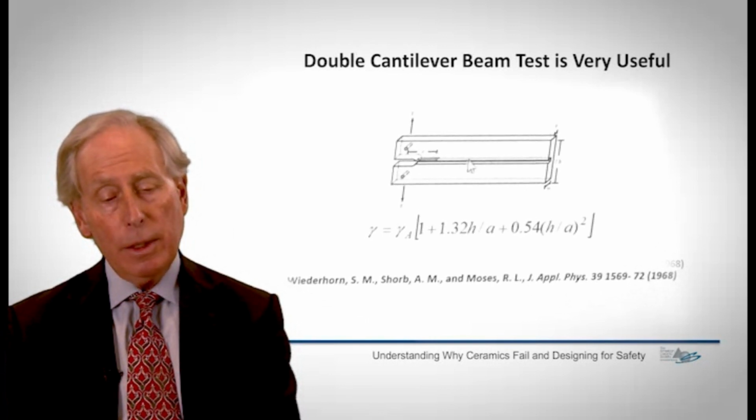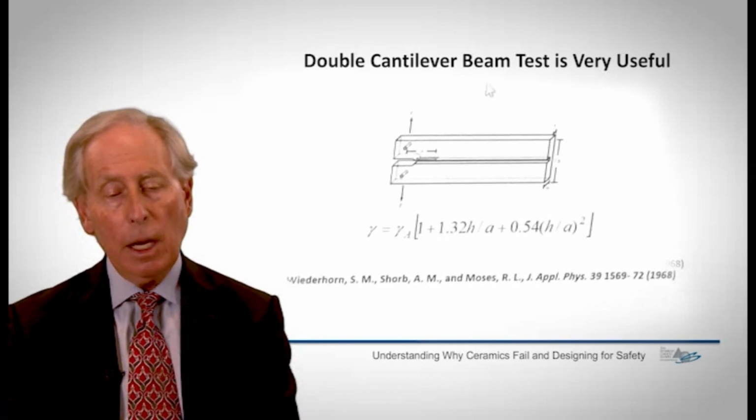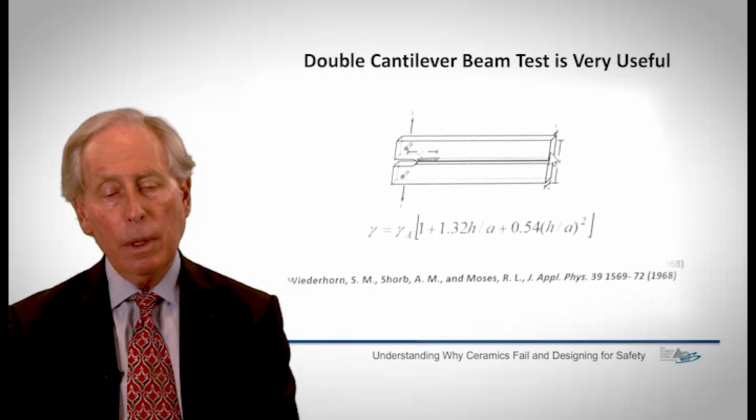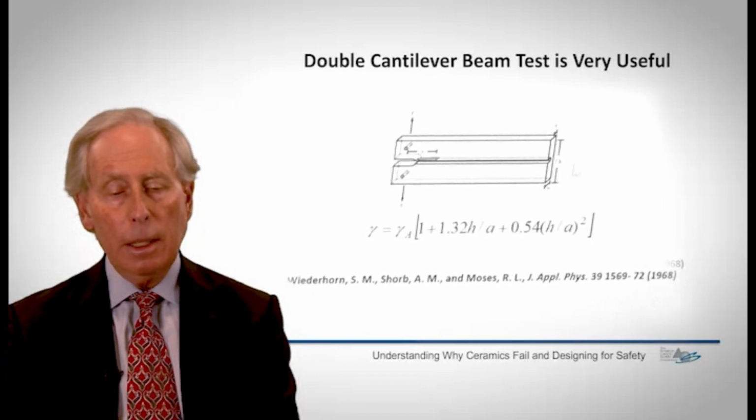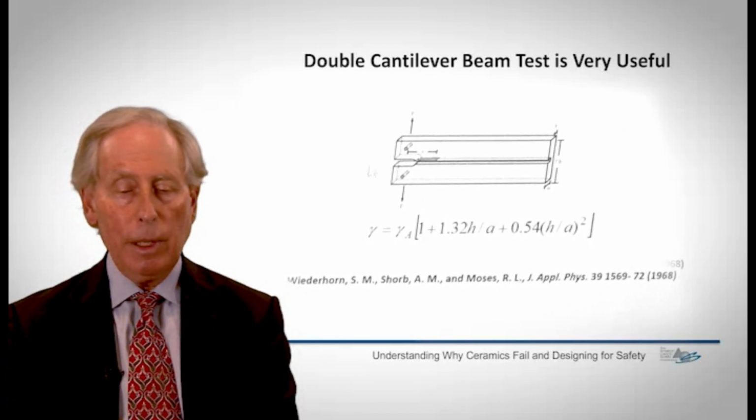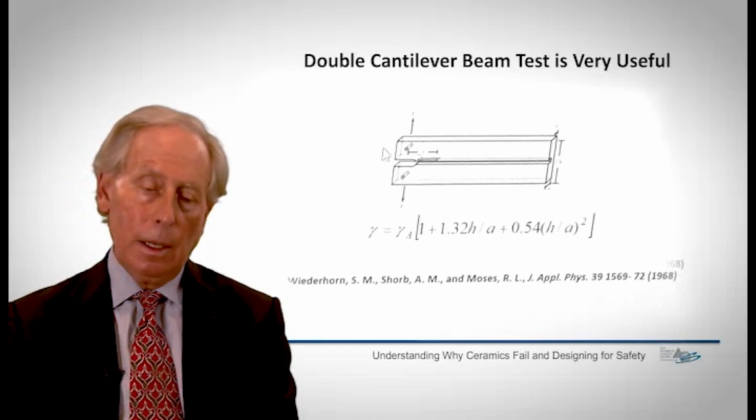One disadvantage of this material, I'll show you later, is that in order to make the crack grow slowly down the specimen, or grow stably down the specimen rather than cutting off to the side and breaking off an arm, you must cut a groove. Unless you have a single crystal in which there is a defined cleavage plane, you must cut a groove in the specimen in which the crack is guided down here.